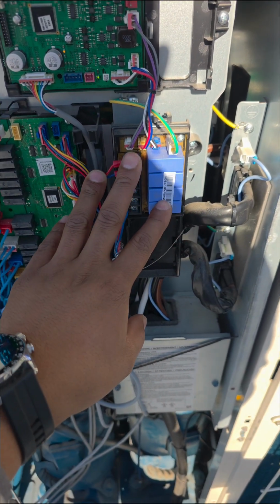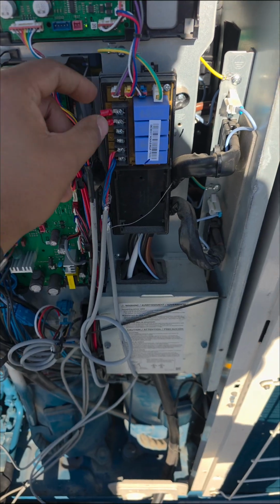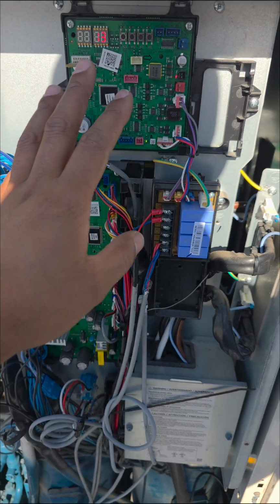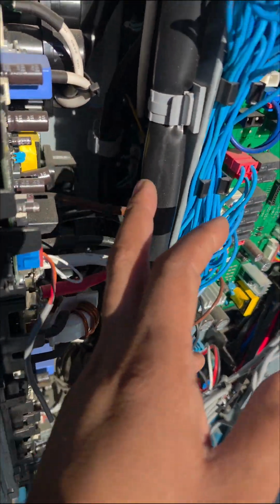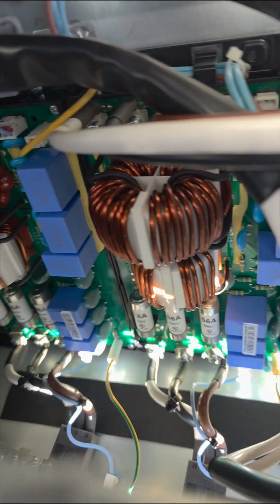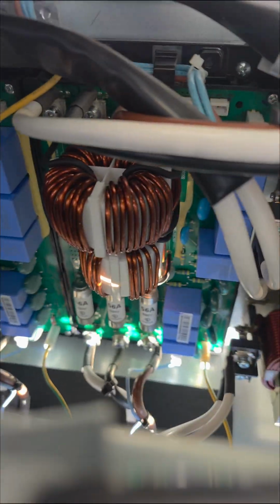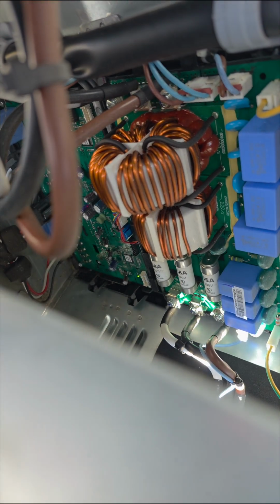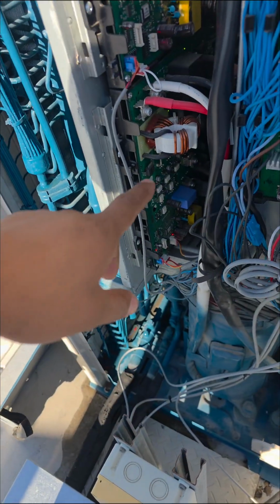So our terminals for comms to all of the indoor units, and that's a daisy chain, that's a loop, comes to our main board over here. This is the brains of everything. We've got our hub board. From the hub board, we've got our, see if we can get in at the back, then we have our EMI filter PC board 2 and 1, and below that we have our fan inverter board, and on top we've got our reactor coils and our inverter 1 and 2.